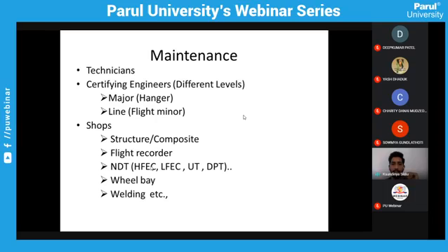And wheel base is nothing but, technically, you say that a wheel is nothing big, but it has its own various maintenance, like how thick the tire tread is and how many layers have worn off, because during landing, and not takeoff, there is huge friction on the tires, and a few times you can observe a spark coming out, right? That makes the outer layer of the tire wear off. There is a certain restriction on how much wear is allowed and how many times you can retread it, and all those things go technically in the wheel base.